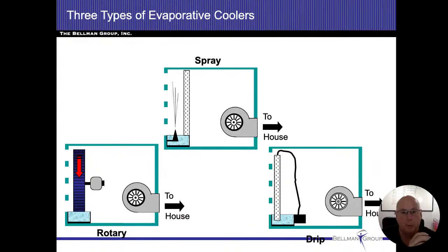One of the items people use for air conditioning is something called an evaporative cooler. It has a nickname of a swamp cooler as well, and it works on the principle of, again, changing state. So instead of using refrigerant going from a liquid to a gas to absorb heat, it actually uses water. The principle is that I add humidity to a building, and that moisture lands on people and on objects.